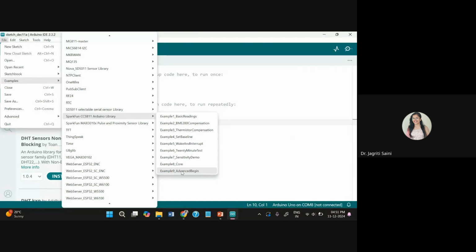When we are talking about gas sensors, you may always need a different set of calibration techniques or sensitivity adjustment techniques. That is essential for your gas sensors. Why do we need sensitivity adjustment or calibration adjustment over here? The reason is, for instance, whenever you are getting a gas sensor from a factory, it is not always essential that it will be factory calibrated.